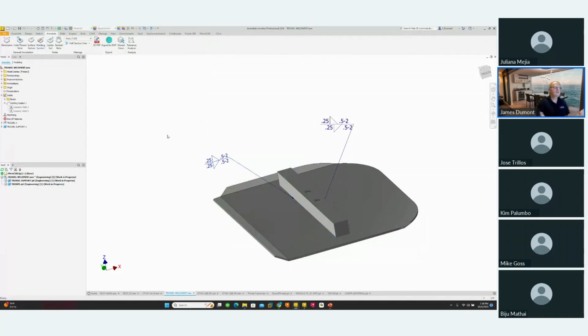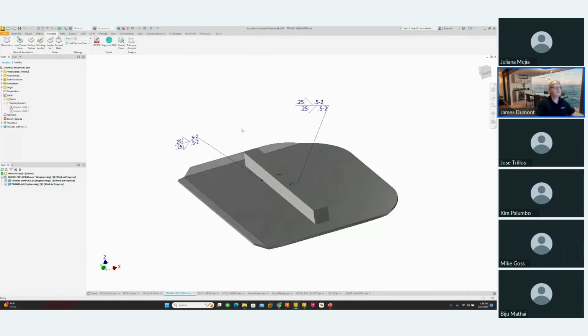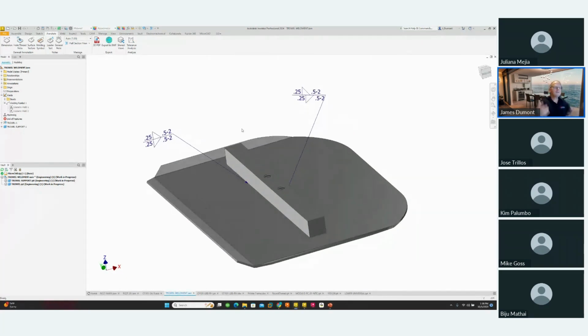And so I'm looking at this like, why would I want one over the other, right? So welds have been around for a long time. They're built into Inventor. Now we have the annotation in this welds. So one of the issues is if I do a 3D PDF, the MBD definition goes with it. The welds does not. So as far as sharing, communicating, collaborating, you want all the information to be there. We can now do it with the annotation versus the actual weld symbology.